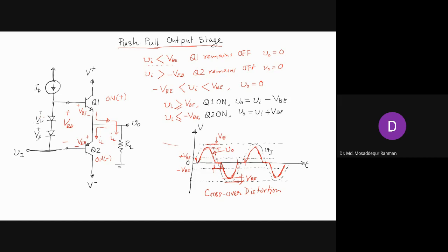Now, the voltage here will depend on this bias current, and this is very critical because you don't want to supply too much voltage here. If this is too much forward biased, it will carry high current, right? High current will start flowing, and that will draw large power from the battery and cause heat dissipation. You don't want that. So you want them to be just forward biased, with minimum current flowing here.